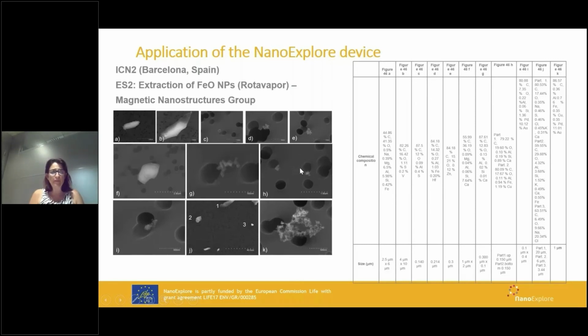That means that it is important to improve the local ventilation in this lab, and also that every user that goes inside this lab has to wear a protective mask in order to avoid possible inhalation of nanomaterials and metals. Also, you can see here that this material is composed of a monoparticle that has a size of 100 nanometers.